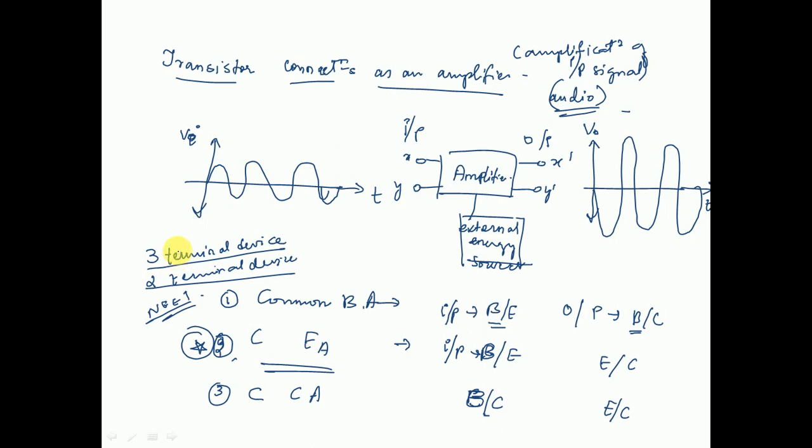configuration being used as a transistor amplifier, let me tell you a little bit more about the transistor phenomena, like how the transistor is actually used for amplification. Let me give you a brief insight into it. The base emitter junction is always forward biased, yes or no? Whenever you have forward biasing, the resistance is low. That is why milliampere current can flow in the forward biasing region, right? So resistance is low.